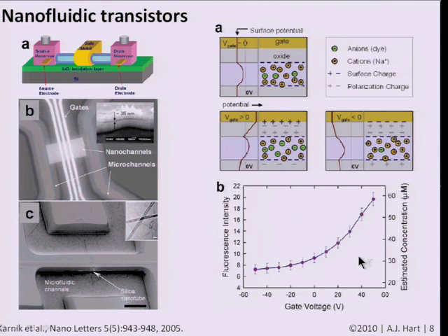Because if you can get more flow through a membrane at the same pressure drop, you can decrease the energy consumption needed for that separation. But it turns out that the concept of the Debye length is very important in that problem, because the practical salt concentrations for what's called brackish water, which is lightly salty water you might find in a saltwater lake, all the way to seawater, is so high that the Debye length is very small, in fact less than a nanometer, and that